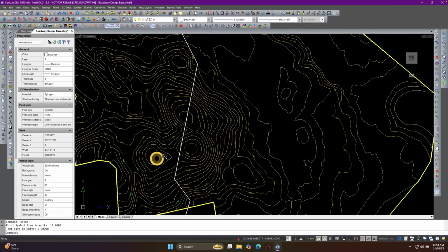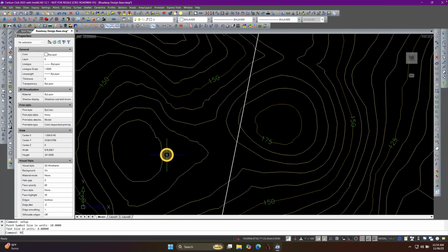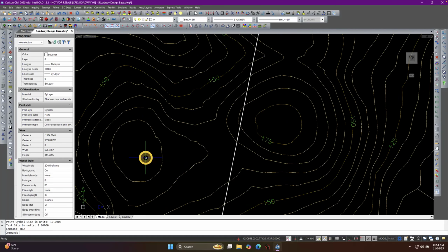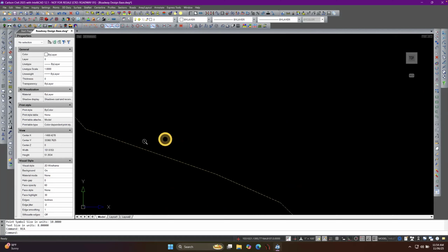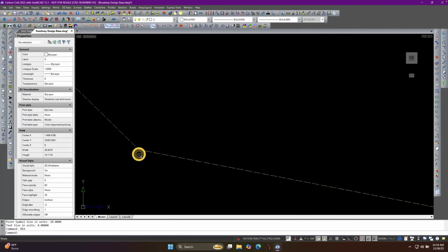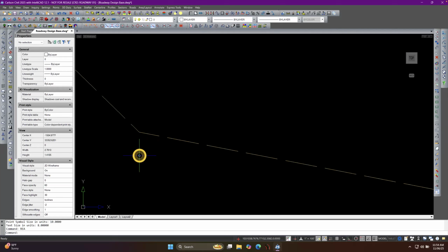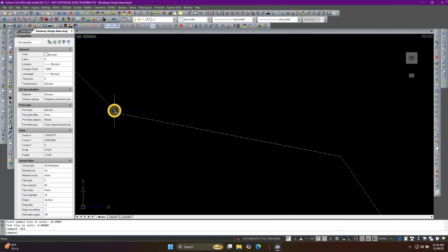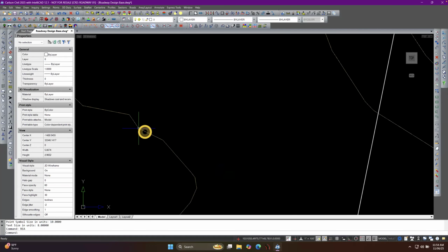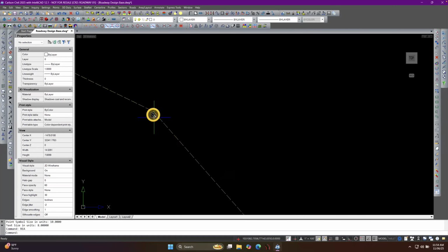So now do a regen, REA is to regen all. Now you see the dashes picked back up, but even at that, they're still kind of close. Now here's what I mean by that going through the corner. See there, the corner, the pattern just happened to be right there where I was able to restart. I'm going to see if I can find that corner that lands in a gap.